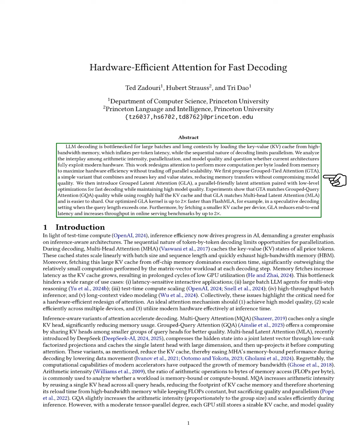During sequential decoding, we observe that the large general matrix multiplication workload shifts to smaller batched general matrix vector multiplication. Each element of the cached key matrix performs one multiply accumulate operation with the query element, resulting in a low arithmetic intensity that is far below the potential of the GPU. This low utilization indicates a significant gap between the compute capabilities of modern GPUs and their memory bandwidth.